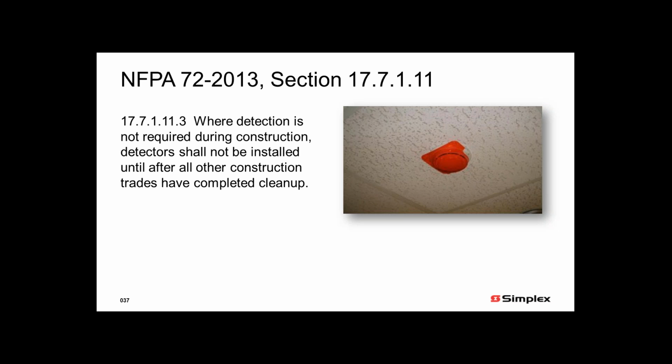We don't want the dust and the debris and the dirt going through the air and getting inside of our smoke detectors. So we tell you that you shouldn't install those. So if anybody challenges you and says, well, where does it say that in 72? Well, Chapter 17, section 17.7.1.1.3 specifically states.